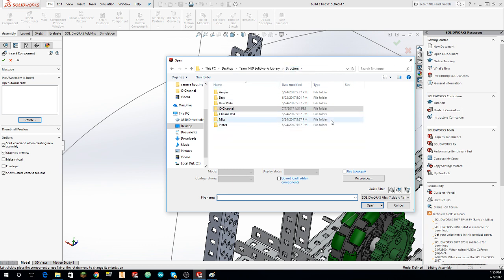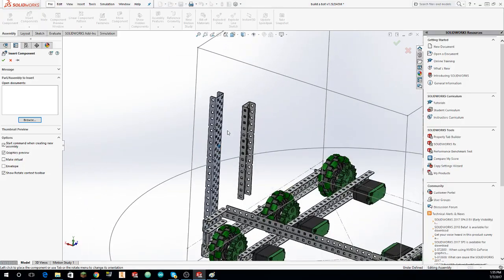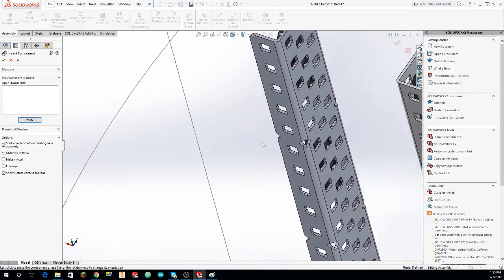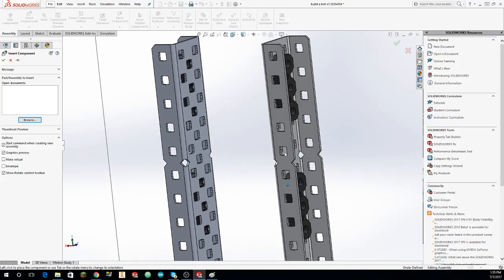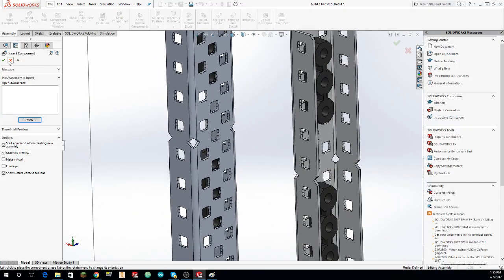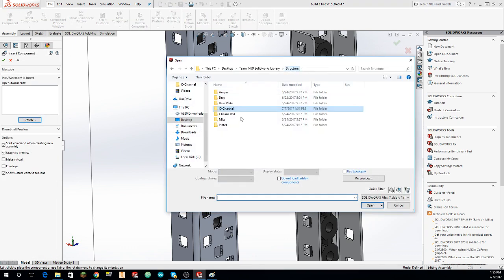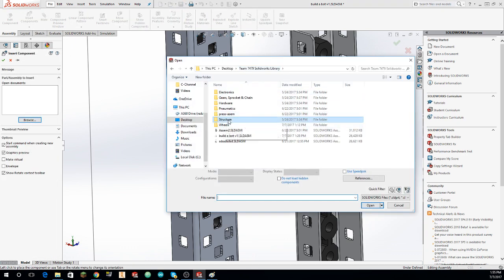Can we actually make these together? I don't think we're actually going to use a gear to connect them together since we're not actually lifting very much weight at all, so I think we can just get away with having some standoffs in the center here. So let's get some standoffs. So in hardware, there we go. Standoffs and couplers.